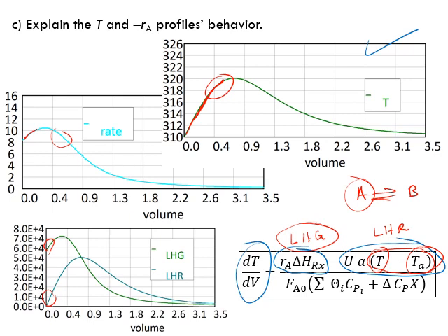However, still the rate of reaction is appreciably high, leading to high localized heat generated. Okay? And this localized heat generated is still more than the localized heat removed, despite the localized heat removed also increasing because the temperature inside the reactor has increased.